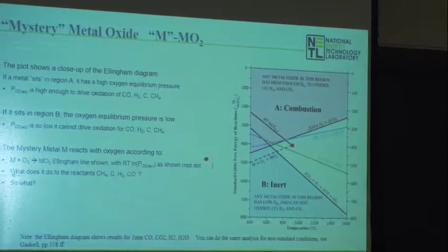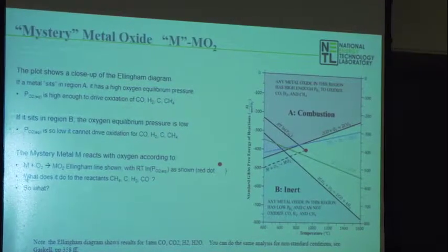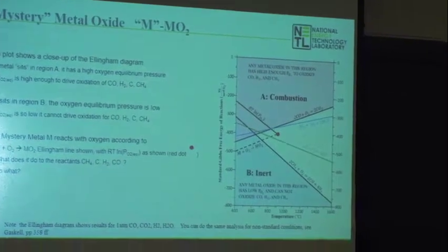It comes up, like, maybe if you got it up to, I don't know, 2000 centigrade, you might be able to reduce it. But it's pretty inert stuff. You make refractories out of it, right? Remember, the development of aluminum was stymied by the fact that they couldn't figure out, until Charles Hall came along and developed the Hall process, because they were trying to reduce aluminum oxide thermally, and you could never get the oxygen partial pressure low enough with conventional fuels, like how you make iron, right? So Hall came along and realized electrochemically, and that's how we make aluminum today, right?